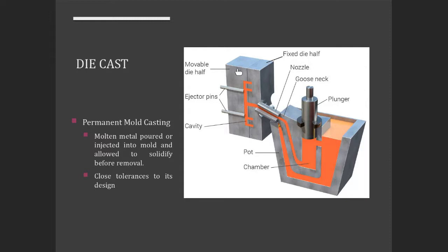The die cast components are nice because they do mold up close to the tolerances of the design that you're looking for, and it has a nice smooth surface because the molds themselves, or the dies, are made out of metal, so the surface is also going to be nice and smooth. Sand, you'll have a more rough texture to it, and you could even encapsulate chunks of sand if the mold was not set correctly prior to the casting process.